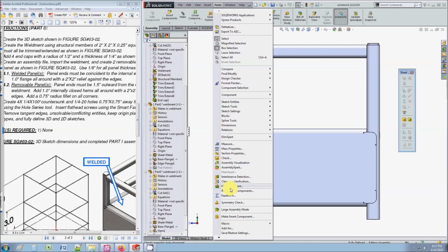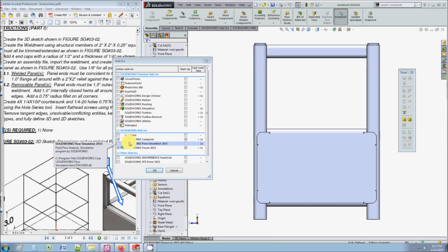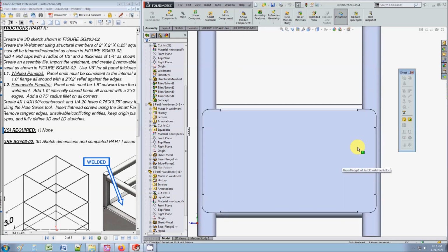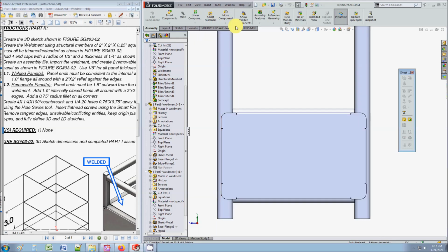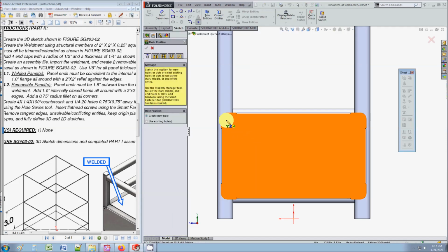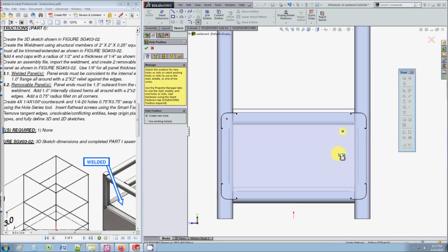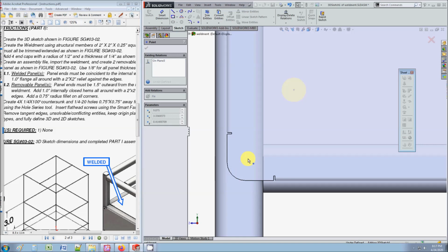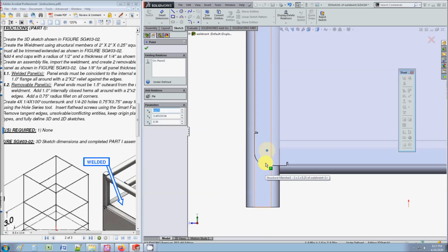So first let's double check to make sure these two are turned on, because they don't turn on by default. So those are the toolboxes. It should be on the documentation for sheet metal, so that should be alright. So we first need the hole series tool, and we're going to hover over there. Yep. And kind of snap. Well, if it doesn't snap, just click somewhere and then try to get the hover over. I know it gets kind of difficult sometimes.